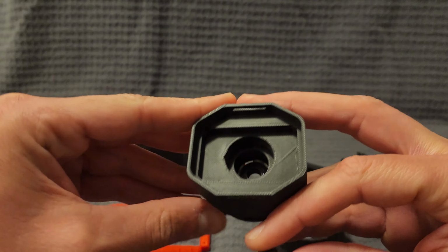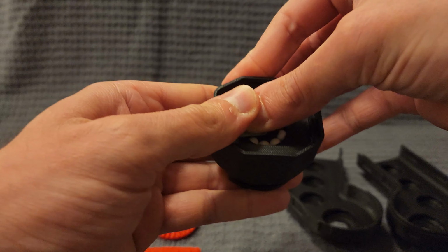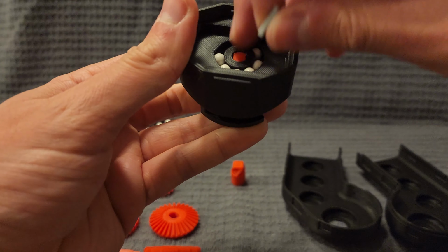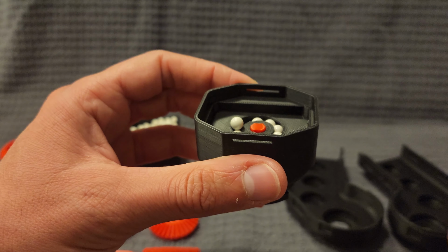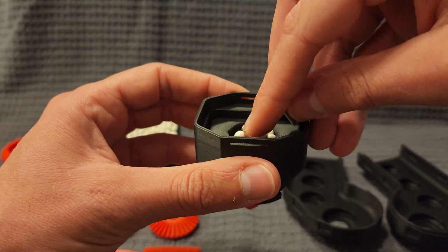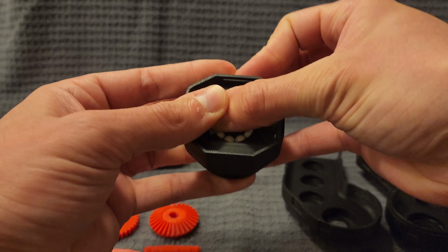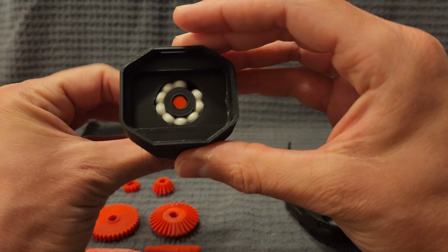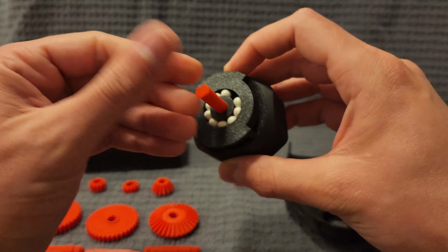I do recommend that for this top bearing track, you use the top shaft to support the bearing races while you are inserting the BBs. When inserting the BBs, it's really important that the scallops on both of the BB components are lined up. That provides you with a hole that you can push the BB through by pressing. Each track is going to hold a couple of BBs, so you're going to need about 150 BBs approximately to do the assembly. But most bottles of airsoft BBs contain at least 1,000 and are really cheap. You can see it spins quite smoothly.